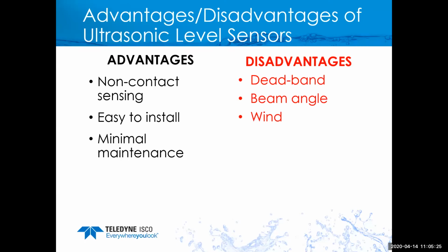Wind could also be a problem with ultrasonic sensors because we are transmitting a sound wave, and the wind can actually take away or reduce the return signal. Think of it as when you're outside on a windy day, you have to speak much louder to somebody so they can hear you because the wind is actually carrying away your sound waves. Steam can also be an issue